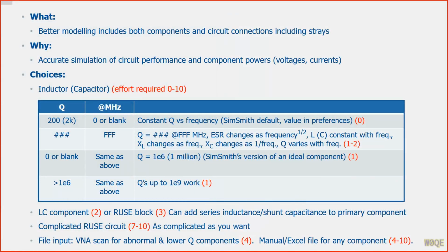The ultimate goal for most folks would be to design a circuit, simulate it, build it, measure its performance, and have the measured and simulated performances match closely. Think of this as the Holy Grail. This requires that the simulation be done with real and not ideal components, and also that the simulation includes significant new components that are the result of building the circuit. Wiring and stray capacitances are new components, as are your RF measurement skills.